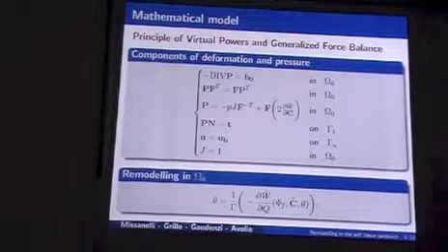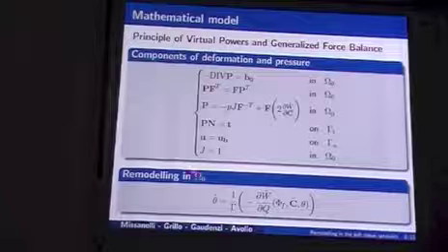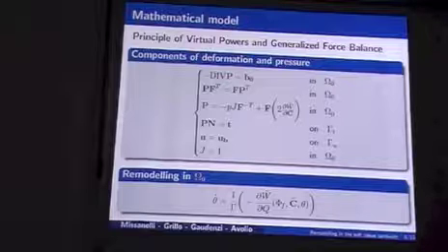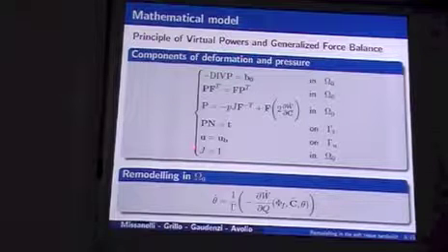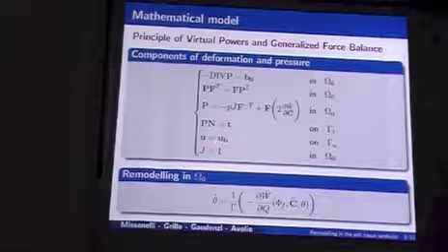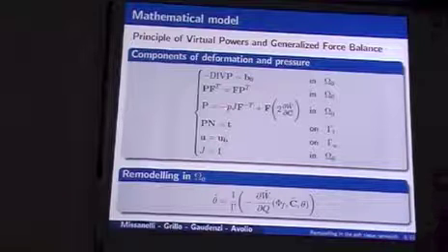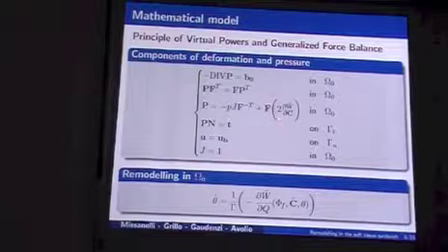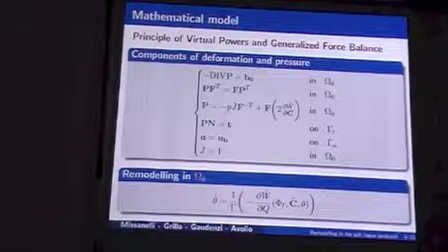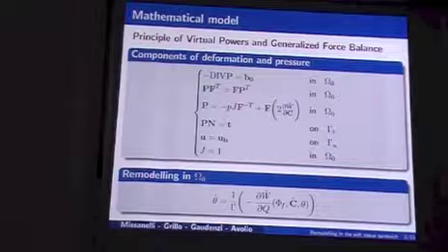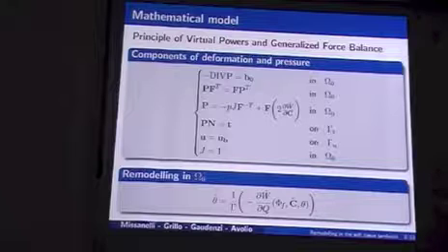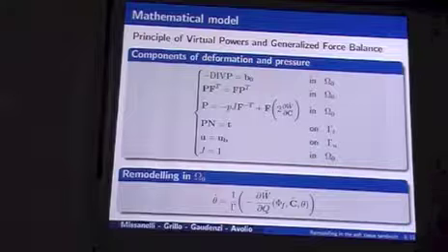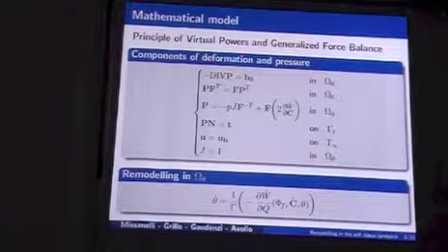The problem is set mechanically in the first part with classical equations. In particular, we constrain the incompressibility here, so we have a pressure there. The constitutive part is taken from the constitutive law. And for the remodeling, we say that the evolution of the orientation of the fiber is described by the variation of the mean angle that we take.